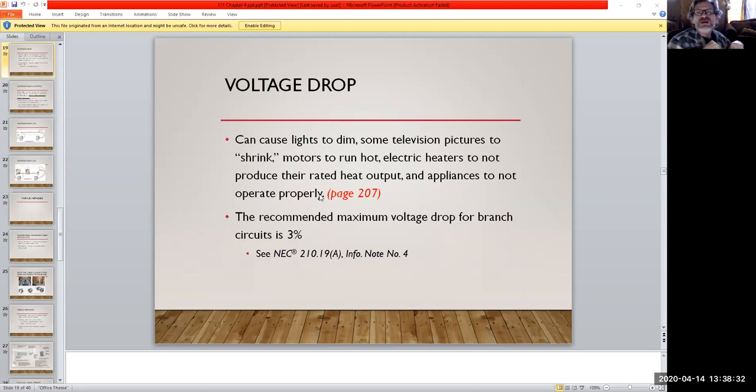Excuse me. So when you do your wire runs, you have to be careful, because if it's too long of a run, your voltage is going to fall too far down and it's not going to work. Whatever you're running to, somebody goes and plugs a device in and it's 97 volts and it's meant to run with 110. Well, it might sort of work, but it might sort of not.